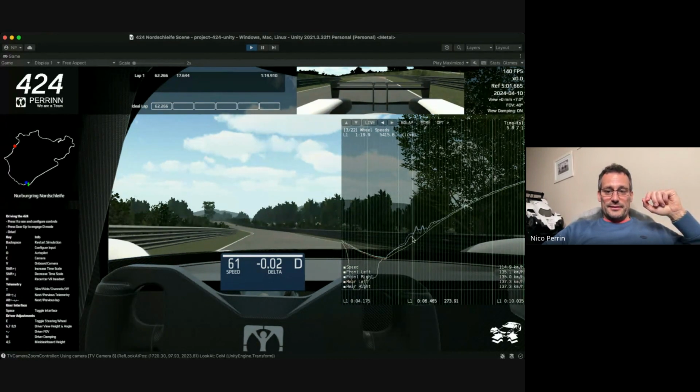If you look at the exits, what we're looking at is obviously the wheels are going faster than the car at that point. You see the car speed is still green. Here we are looking at positive slip. It's a four-wheel drive car. We want to see, is it the front or the rear that slides the most? In fact, if you look here, first of all, the left and right go at exactly the same speeds at the front and at the rear. You can see 1.9 left and right, and the rear is very close as well.